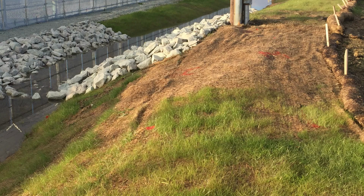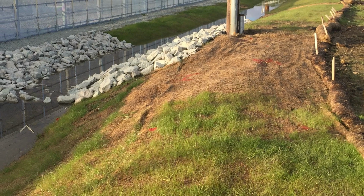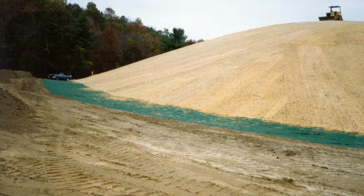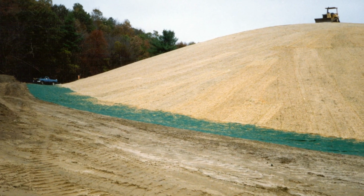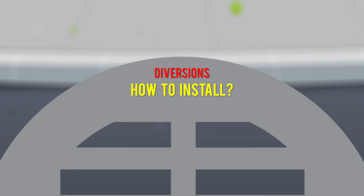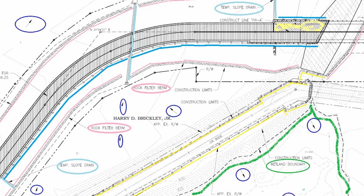How does it work? It works by temporarily directing stormwater runoff in a controlled manner to a desired location and protects work areas from stormwater runoff. It can also be used to manipulate watershed areas for sizing of sediment controls and measures. How to install. Construct the diversion to dimensions and grades shown in the construction plans.